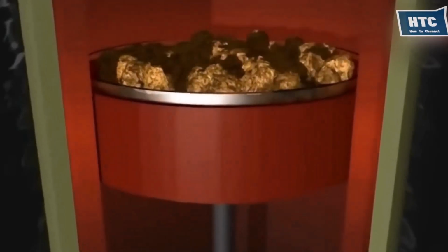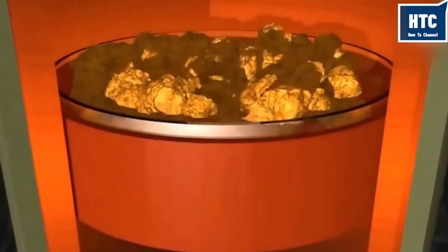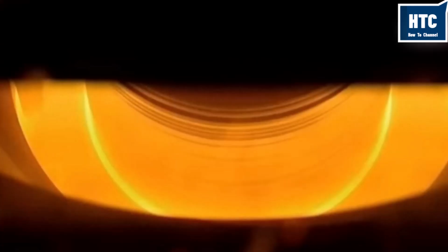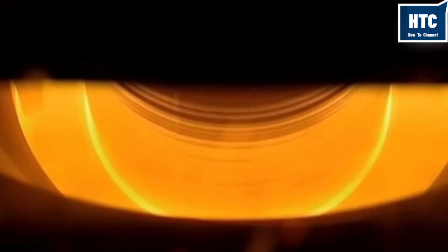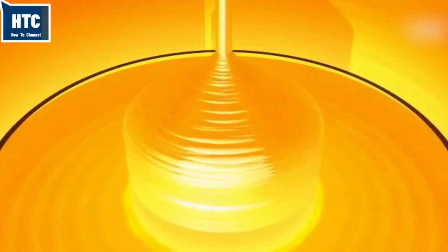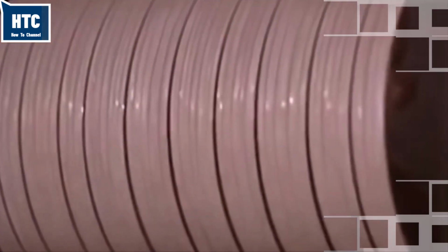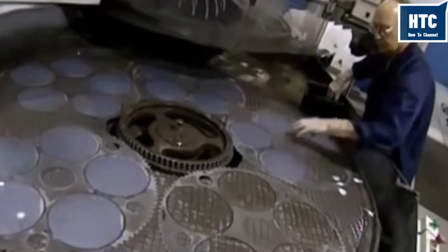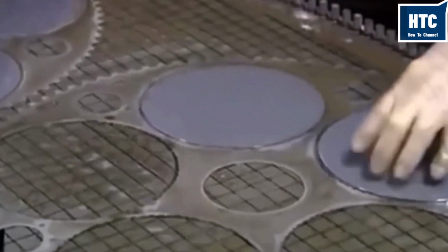Next is the Czochralski process. We melt this hyperpure silicon in a quartz crucible at 1425 degrees Celsius. We lower a seed crystal, a pencil-sized piece of silicon with a perfect atomic lattice structure, into the melt. As we slowly pull it up and rotate it, the molten silicon mimics the crystal structure of the seed, freezing into a solid cylindrical ingot. This ensures that the atoms are perfectly aligned, providing an unobstructed path for electrons to flow.